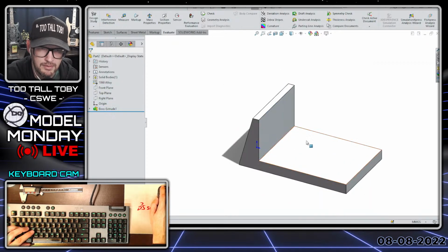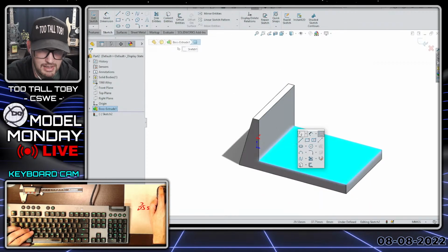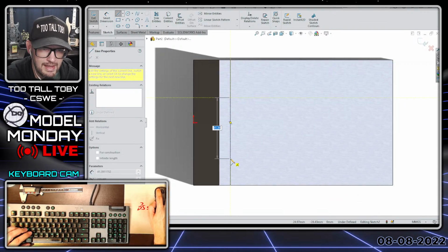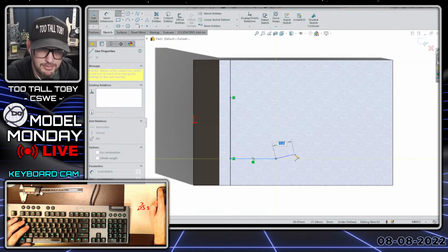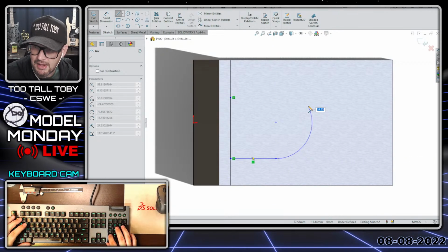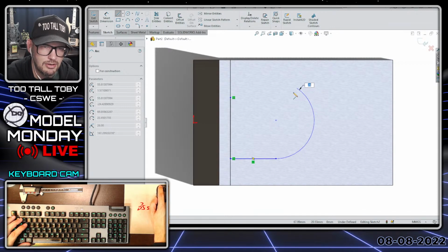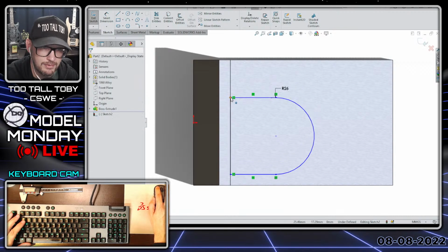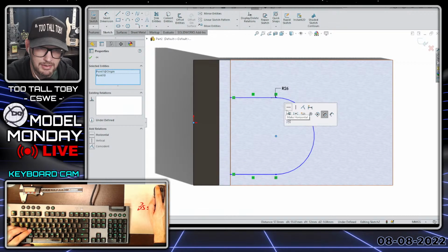then right mouse button. Now this face here, begin a sketch, orient my view, S key, and maybe I will go to the top here. Click a line that comes over, a line that comes over, a line that comes out, single click, come back, touch the end point, come out and around, and then give that a radius of 26, enter. So that line, arc, line, and then typing in the radius can be a huge time saver if you can learn and kind of predict how it's going to behave.